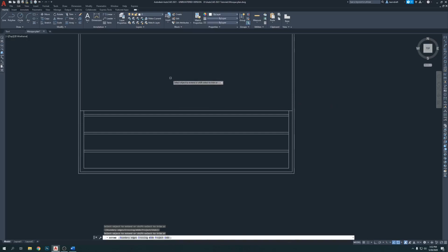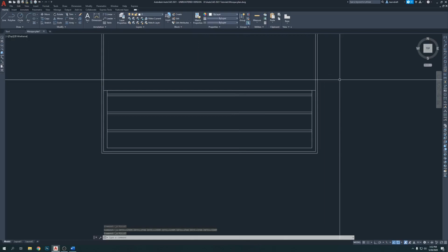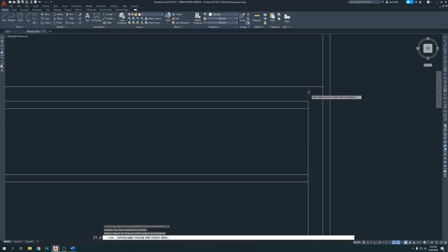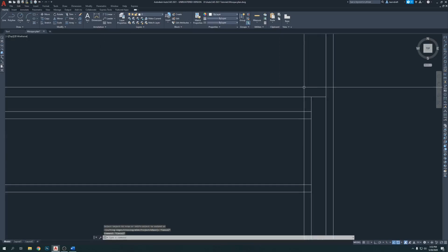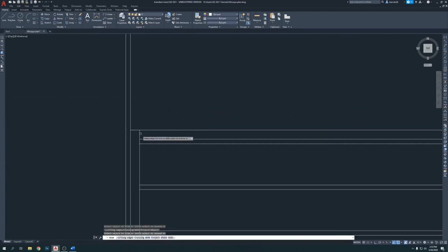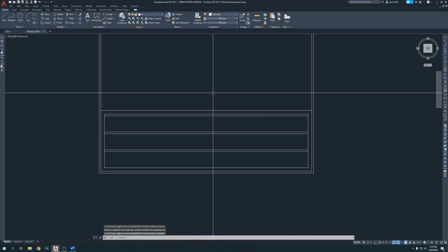It directly goes without selecting the boundary, and just takes the corner out. TR. Enter. Select this line. Okay, TR. Enter. Again TR. Enter. Select this line. Wow, 21 is very, very special. Do not need to make a lot of extra commands.